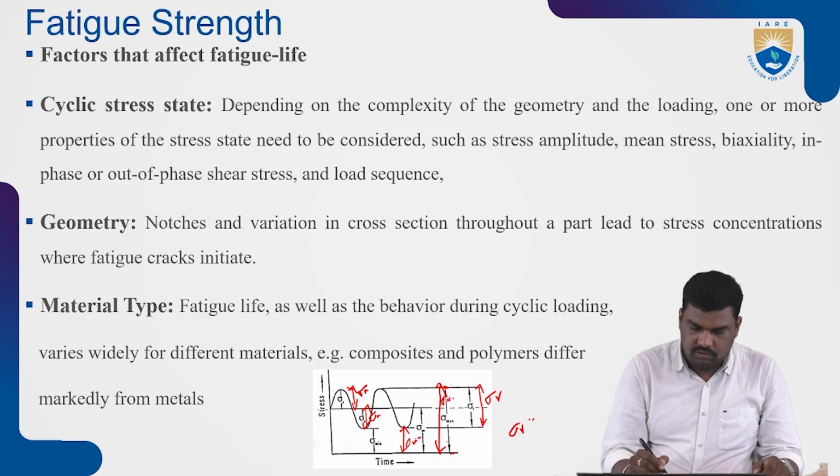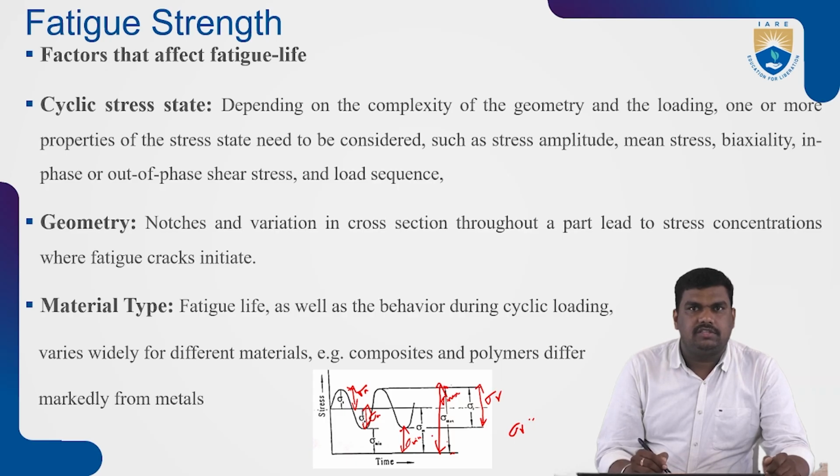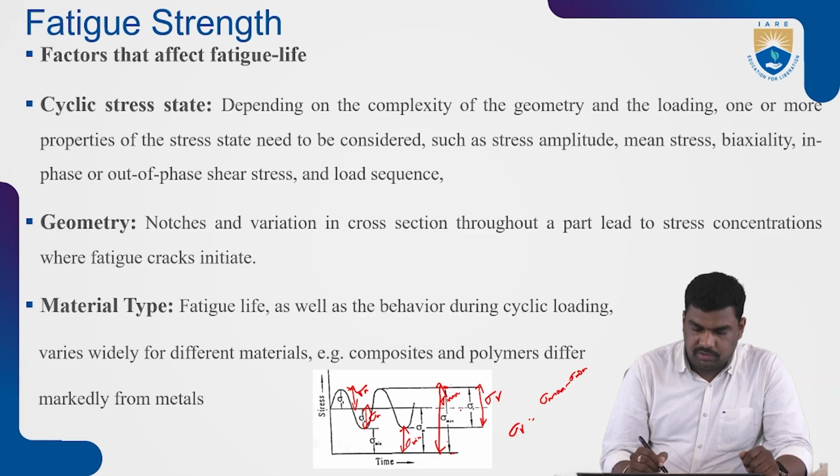This is your sigma max. Now you see the range of stress is sigma max minus sigma minimum. That is your range of stress, right? Similarly, next is mean stress. You can see here this is the mean line, from the bottom.